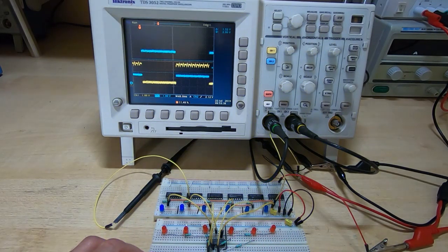Many years ago I once spent 2 entire days trying to track down an error on a £100,000 piece of equipment that was giving spikes in the output readings. It was a scanning spectrophotometer, and the output readings every now and again would give a huge spike. Now the system used discrete logic for the A to D converter. It's a huge board with probably 150 devices on it, a dual slope integrating A to D converter.